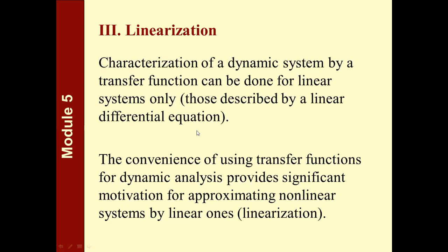We cannot go on with the usual procedure of determining the transfer function if there's a particular term in your differential equation that is not linear or has an exponent. The variable we're referring to here, for example, is the h in the liquid level system, which has an exponent other than 1.